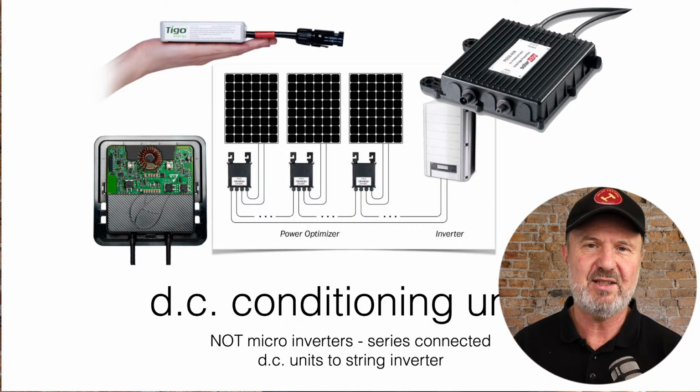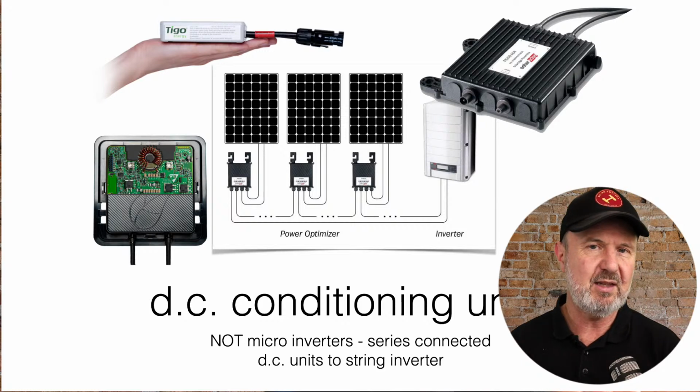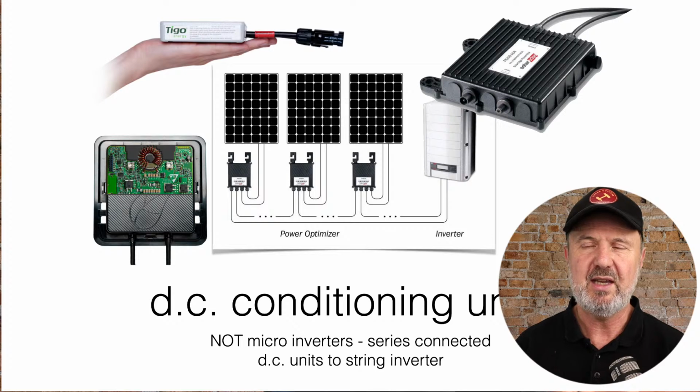Imagine putting a DC isolator under every panel on every optimizer. So we clarified that in the 2014 edition and said, no, not required. They're a special purpose of equipment. We still need isolation on the array, but not on every single DCU. So that was a big plus.